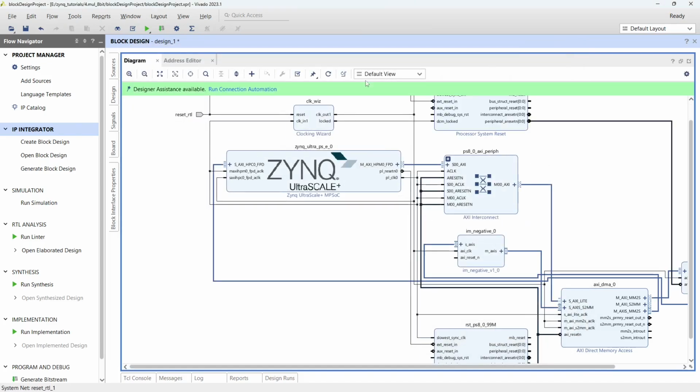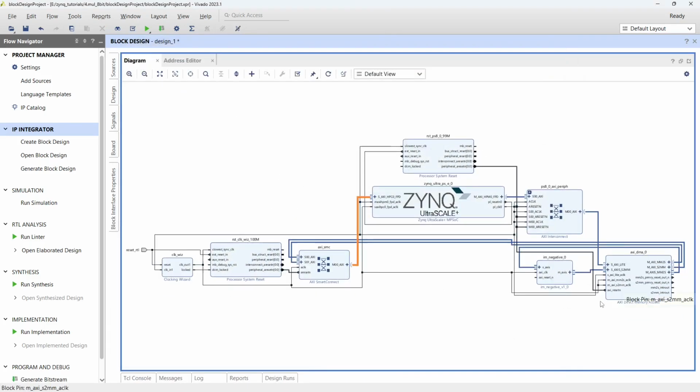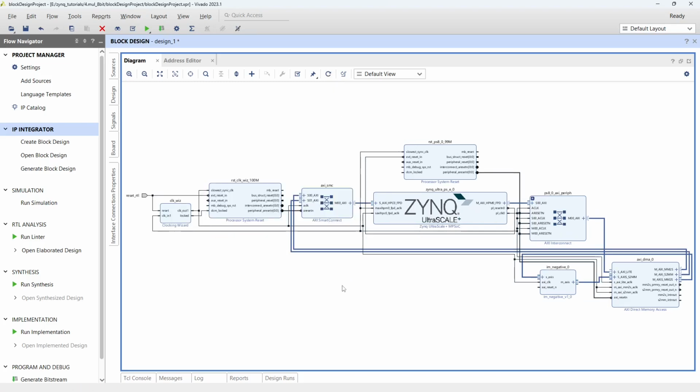So you will have, see, AXI smart. Where is AXI smart? AXI smart interconnect. So that connects this master to AXI smart, and from there to the PS. Okay, so one more connection is missing. That's why the tool is identifying that. We'll connect that also. Now it's done. Okay, so through these two wires, it's being managed. The data will be received here. So we are done with all those things.